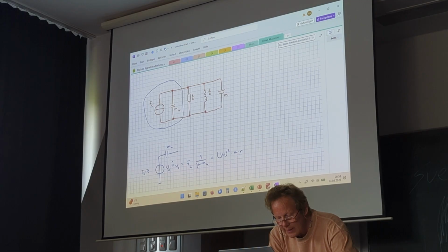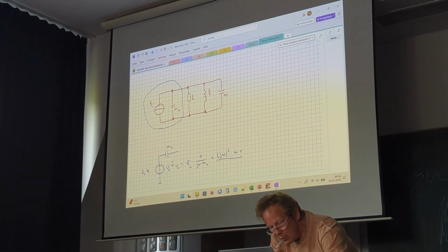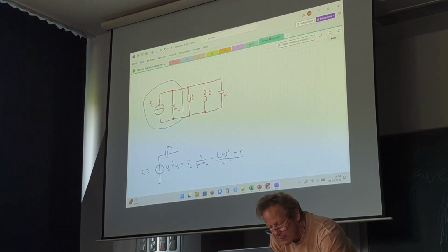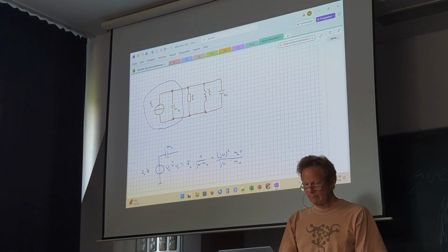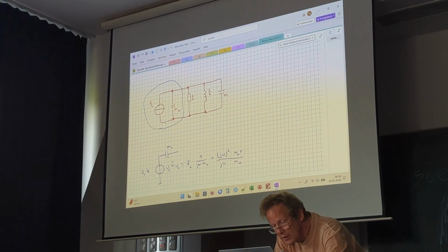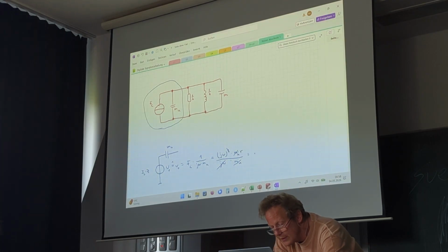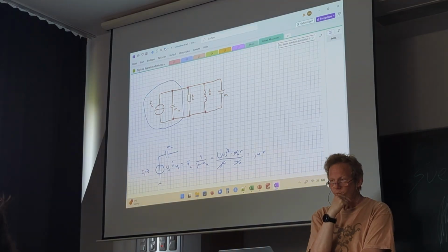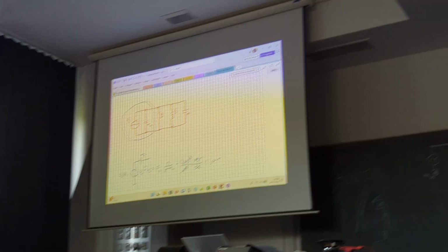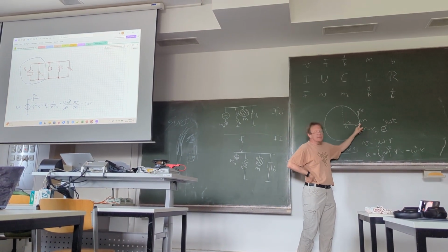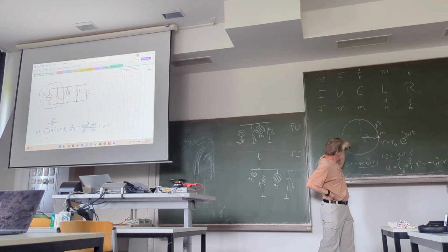So this replaces Fc, and we divide this by j omega and the mass, the same mass by the way, mu. So a lot of things cancel out, 1 over j omega and mu, and what's left is j omega times r. J omega times r, and that really is a velocity. It's exactly the velocity of this unbalanced mass, which rotates around the shaft.